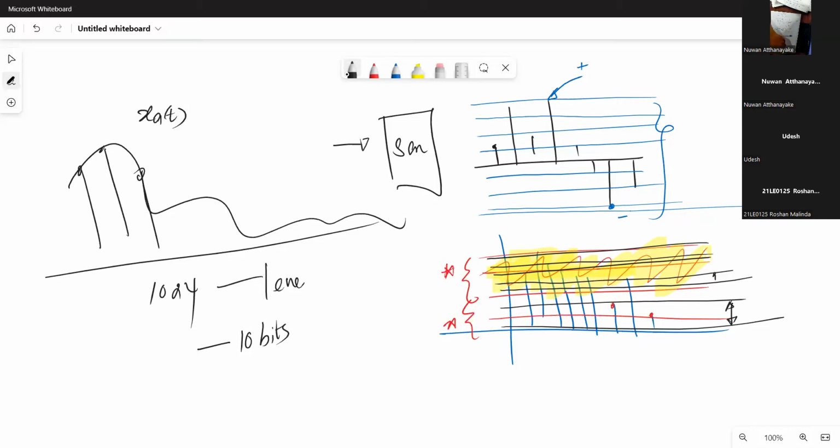This is a binary coded word, which means we can have two states, ones and zeros. So you can simply take the log base 2 of 1024, which equals 10, which means each and every sample is coded with 10 bits. Once you split this entire space into 1024 levels, you can approximate each sample to the neighboring quantization level.